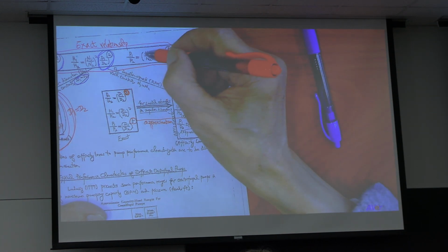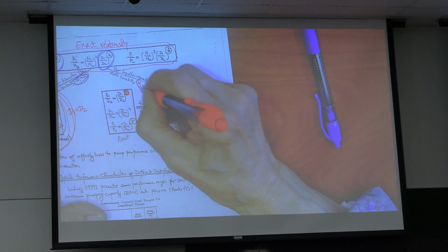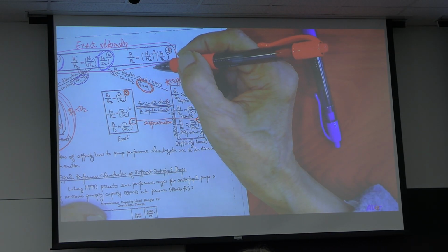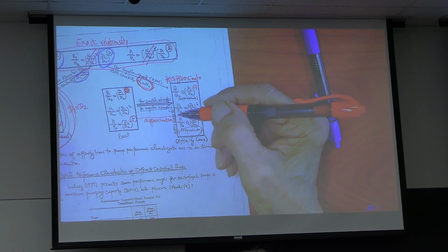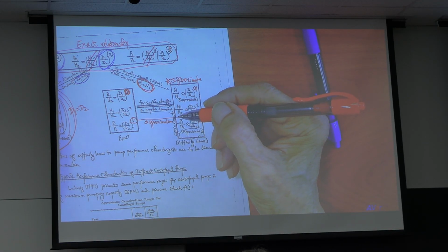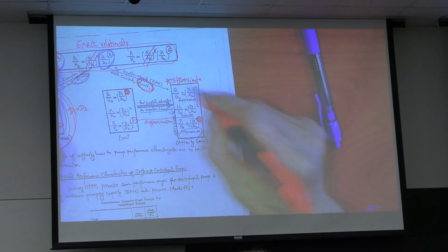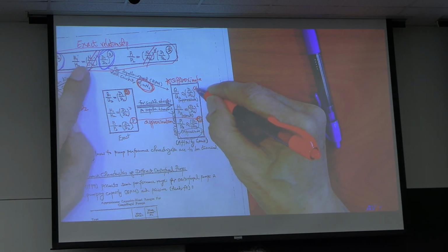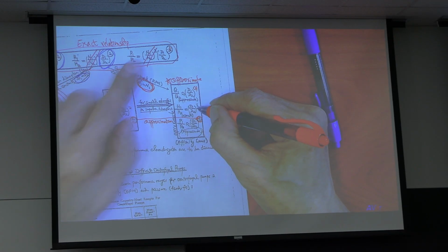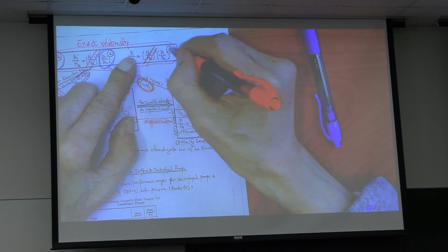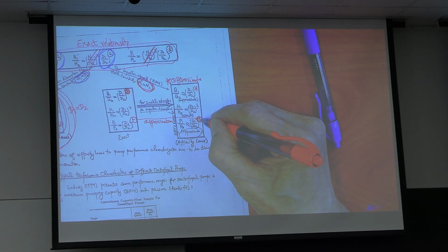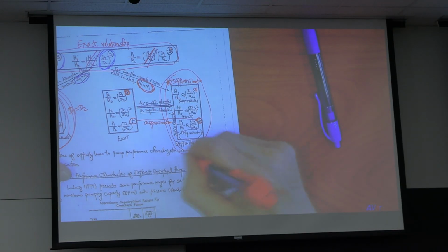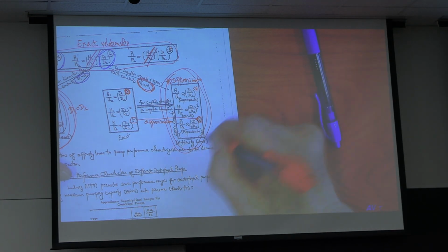Okay? When the impeller speed N is equal, you drop that term. First one, you force the third power into a linear relationship. Second one, stay. Third one, fifth power, you force that to be 3. You call this affinity law. That is approximate, not exact.